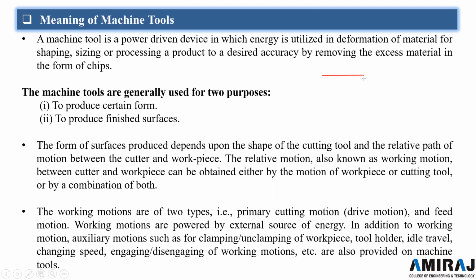So this is the shaft after we cut it. This is our tool, and the primary motion is given to the shaft, and the tool will have the feed motion, which means it will be traveling.